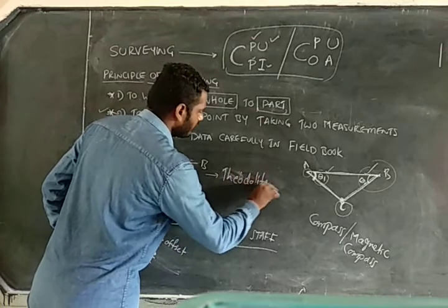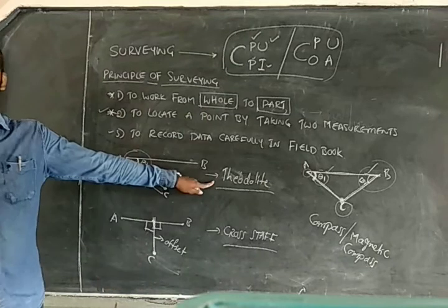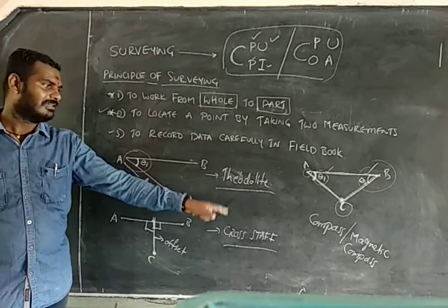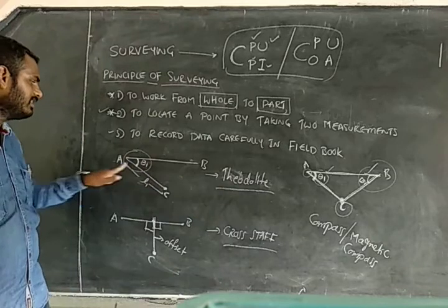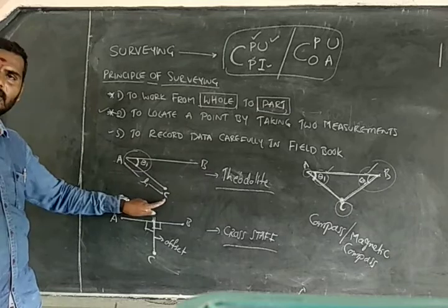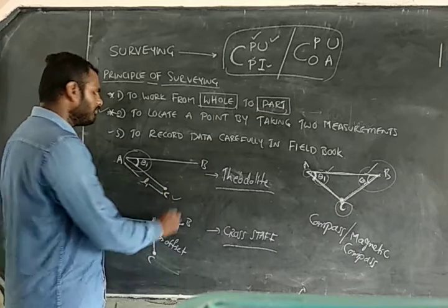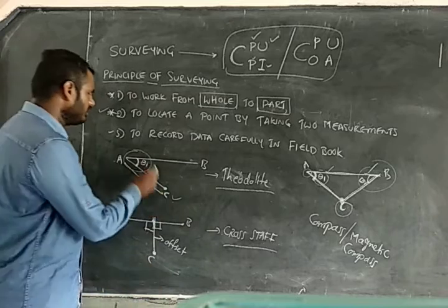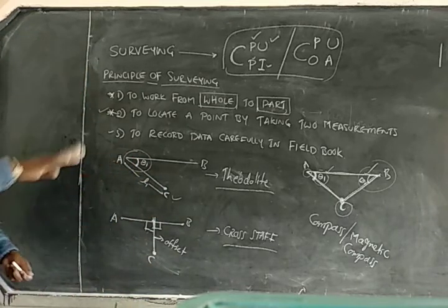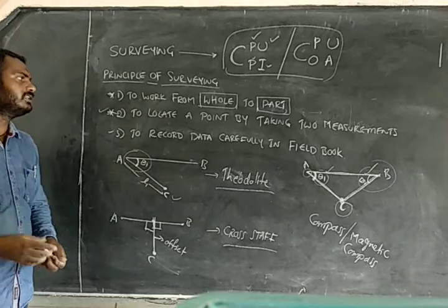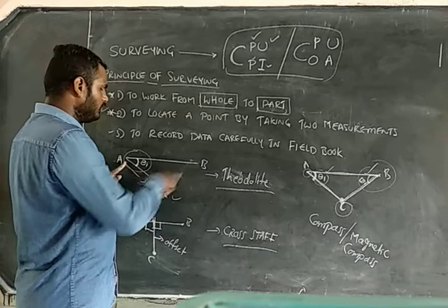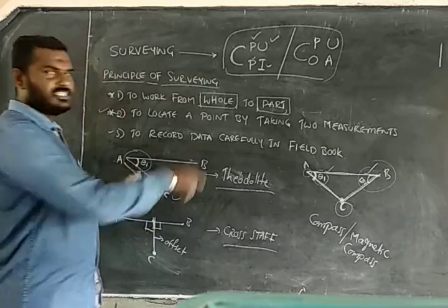theodolite. Theodolite. So it's an instrument which is really very helpful to measure both vertical and horizontal angles. Okay, by taking accurate horizontal angle theta 1, either at A or at B, and by making a measurement L1, you can locate a new position that may be C, that may be D, anything. Okay, so this is another method to locate the new point. So this is how in four ways we can locate a new point, depending on measurements. At least two measurements are needed from the reference positions.